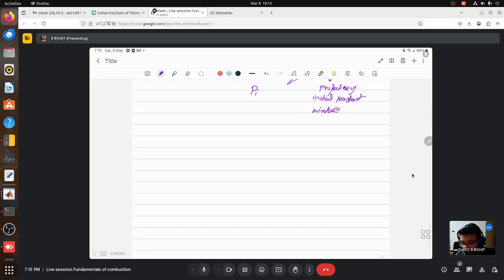In order to do this, your experiments are repeated for different fill pressures, the inlet pressures that you have, and the results are plotted as a pressure temperature curve. So the PT curve is plotted, and it is used to identify the ignition, auto ignition or the explosion limits for different reactant mixtures that you have.